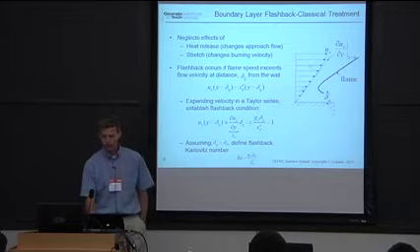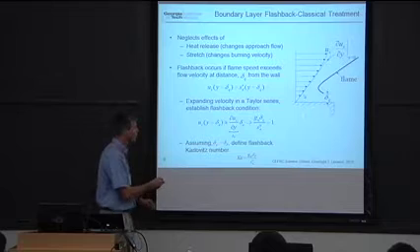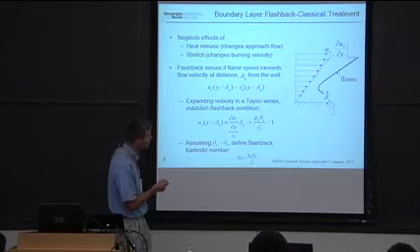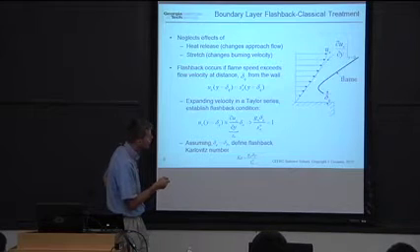So basically the idea is this. If we zoom in on the boundary layer, what I'm drawing here is the velocity profile. You have some axial velocity, which I'm denoting as u_x, and then there's this gradient at the wall. I'm calling it du_x/dy at y = 0.